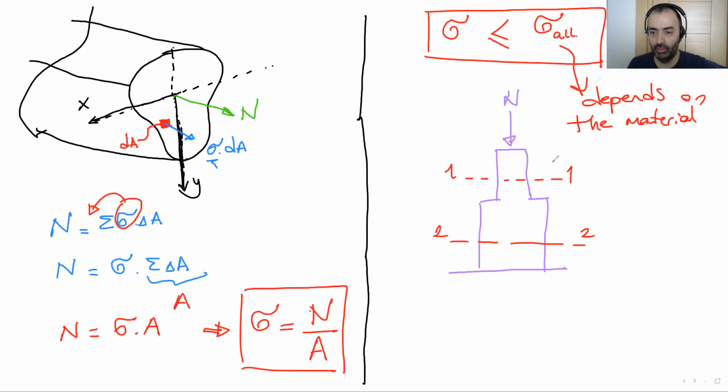Okay, you know, axial force is axial force at each area. So we know that sigma equals axial force over area. So what are we looking for? We are looking for the maximum stress. If the area goes down, if we have less area, since the force is constant in this example, the stress gets its maximum value.